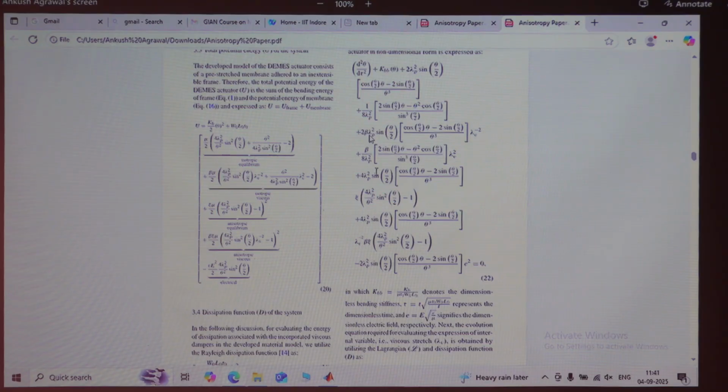So you are saying that the proportionality constant means how different your shear modulus is from the spring shear modulus. Usually it is observed to be 2 times. For example, the upper spring has 30 kPa. Usually the spring in the Maxwell element will have 1.5 or 2 times the shear modulus of this. So we have considered the value initially as 2. So beta is a proportionality constant. That value you can keep fixed or constant at 2.